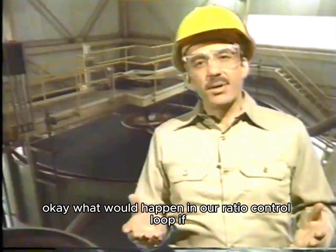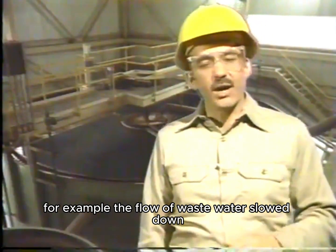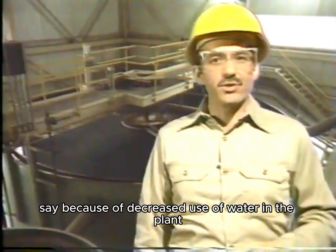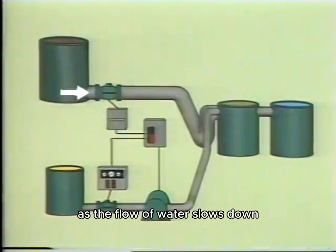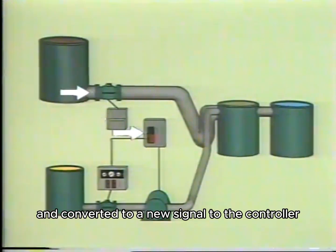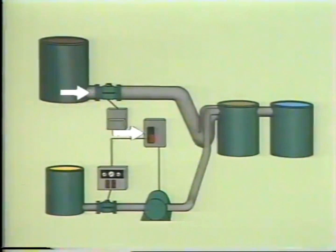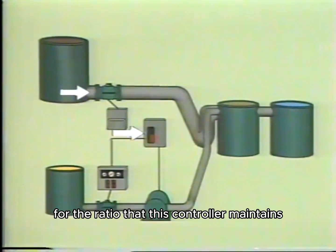Okay, what would happen in our ratio control loop if, for example, the flow of wastewater slowed down, say because of decreased use of water in the plant? As the flow of water slows down, the new flow is measured at the transmitter and converted to a new signal to the controller. This new controller input signal becomes the new set point for the ratio that this controller maintains.